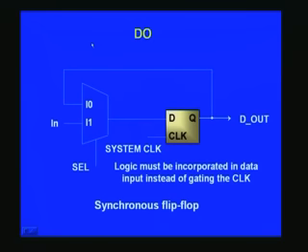After all, what you want is to process the data for different conditions, which you can do by using a mux like this, and your input data can be fed to one of the inputs. You can interpose once again a register here, a D flip flop, the mux output being input to the D here, and once again a system clock separately routed to the clock input of the flip flop, and Q fed back to one of the inputs. This means D out is preserved when I0 is selected.